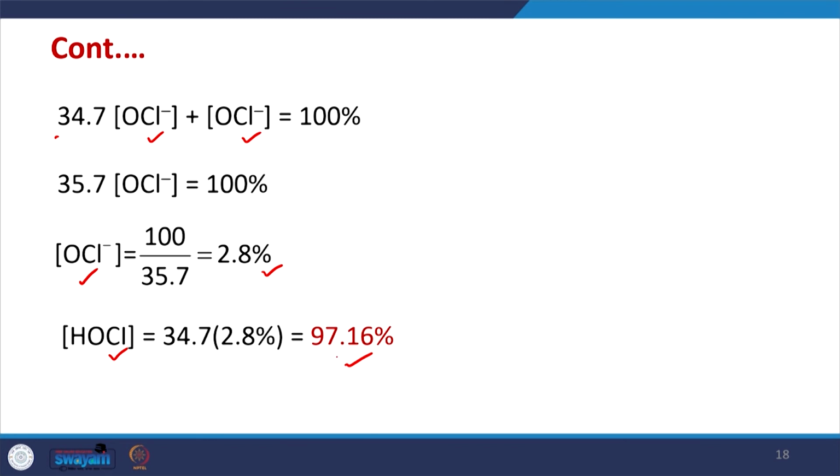it is 97% of the chlorine or hypochlorite added that will be in the form of HOCl. From this we get to know the different ideas which can be used for calculation of the concentration of different chlorine species from the data that we have.